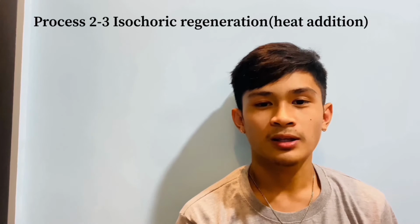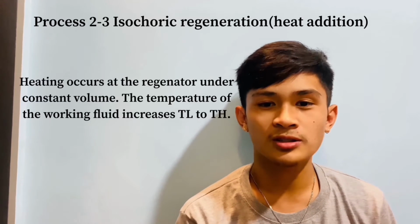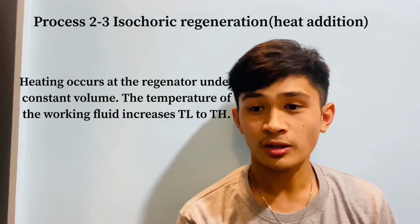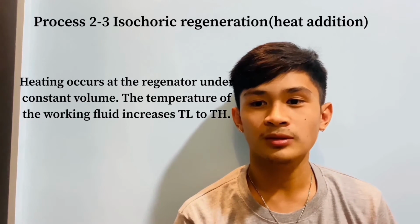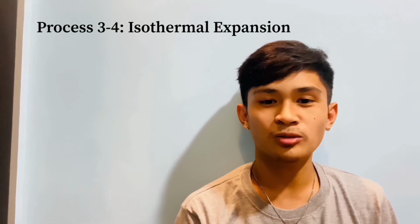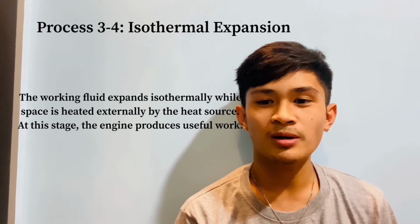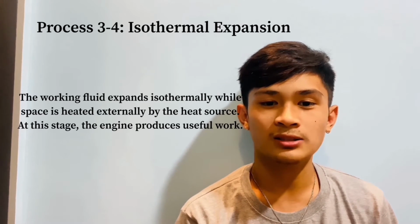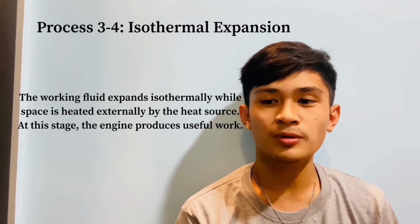Process 2 to 3, isochoric regeneration, heat addition. Heating occurs at the regenerator under constant volume. The temperature of the working fluid increases from T sub L to T sub H. Process 3 to 4, isothermal expansion. The working fluid expands isothermally while space is heated externally by the heat source. At this stage, the engine produces useful work.